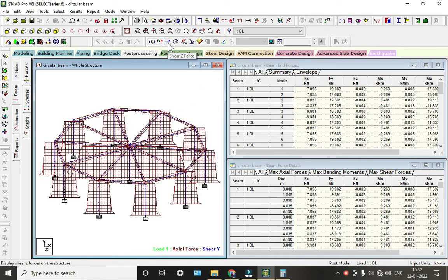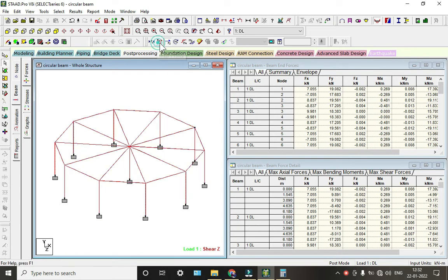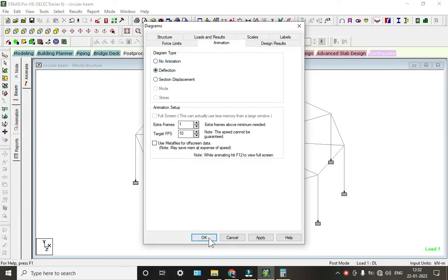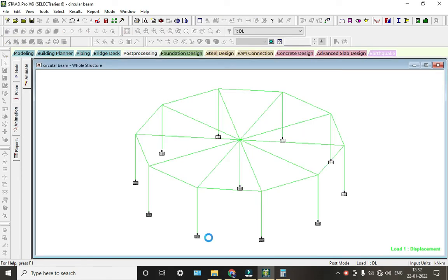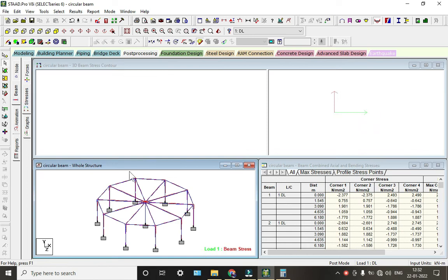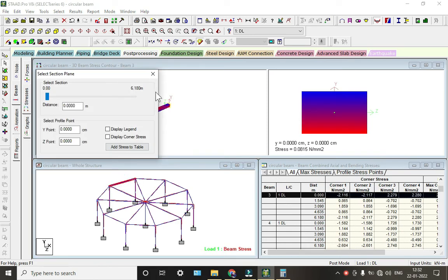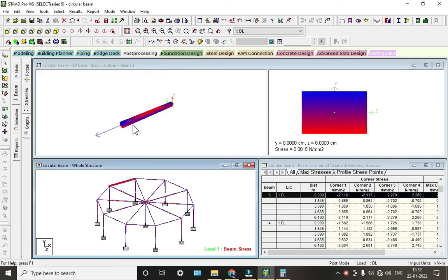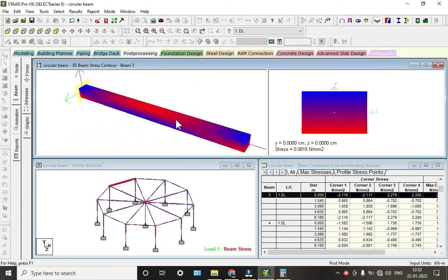You have to select all the beams, or else go to top view, you can select all these beams. Go to 3D. Click on assign to selected beams, assign and save. Then assign design column, select beams parallel to Y, and select nodes. Now we will analyze this structure.